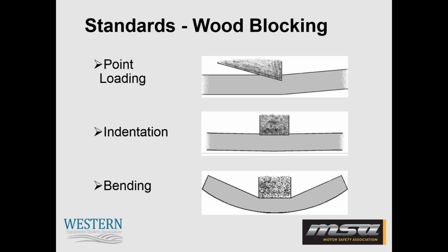Also, I'll touch a little bit on, as I talked about before, storing your blocking indoors. When we have frozen blocking, it's likely to splinter more easily and also be very slippery. So the best practice with that is to bring that type of blocking indoors into your facility overnight and then use it the next day if you have frozen blocking.